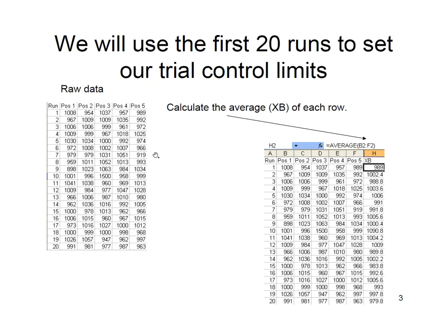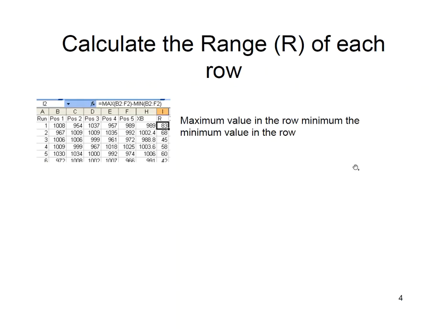That's why the Filmetrics will do this for you, but you have to be very exacting about this, because if there's anything wrong or a typo, it throws everything off. So the first thing you do is calculate X-bar, which is the average of all 5 positions, okay? Then you calculate the range: the highest, the thickest, minus the thinnest, right? And that gives you the range. You just subtract min from max, so it's always positive, okay?